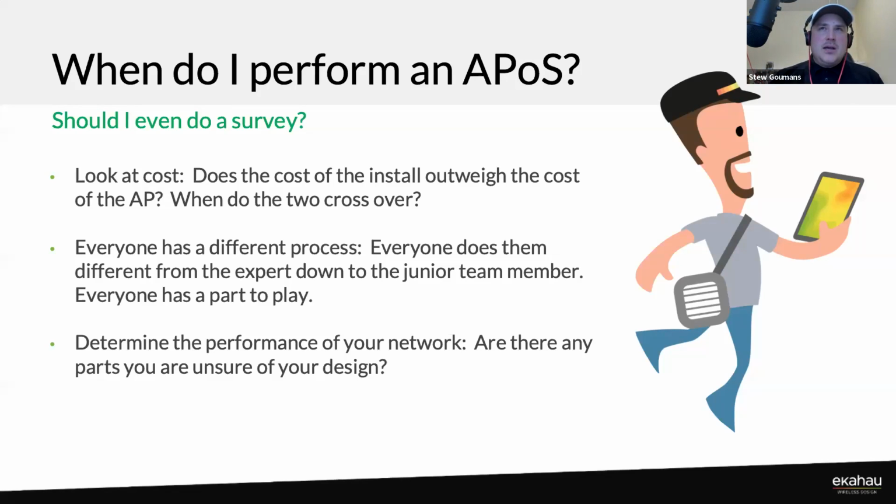Sometimes you may know, okay, I might need to go with an internal AP, but also bring an external. As you can see up behind me, you can use a dipole antenna or the monopole antenna, which I'm showing on the camera now, because you never know what type of environment may require a different way of thinking and understanding the complexities of RF. One thing I learned early on, gaining knowledge from maybe Sam as well, and Jake as well, is to try a different antenna, right? Because even though that may look like a location where you could get away with an Omni, the areas around you, like Grant said, can have shelving in the middle of the way, and you may need something better to down tilt that. So bring multiple antennas, whether it's a patch antenna, a little bit more power, and try different things.